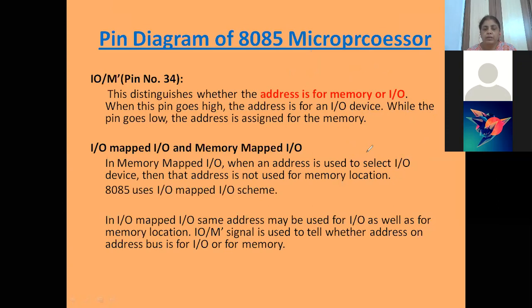तो what happens to peripherals? Peripherals also have some address. ठीक है, अगर ये सारे एड्रेस 0000 से FFFF तक सब मेमोरी के एड्रेस हैं, तो what is the address of our input and output devices? अगर सारे एड्रेसेस मेमोरी को दे दिए, तो बाकी एड्रेसेस कहाँ हैं? इनपुट को कहाँ से मिलेगा एड्रेस? What is the address of output devices और input devices which is connected with this IC? So we don't have extra address because all we have given to memory.